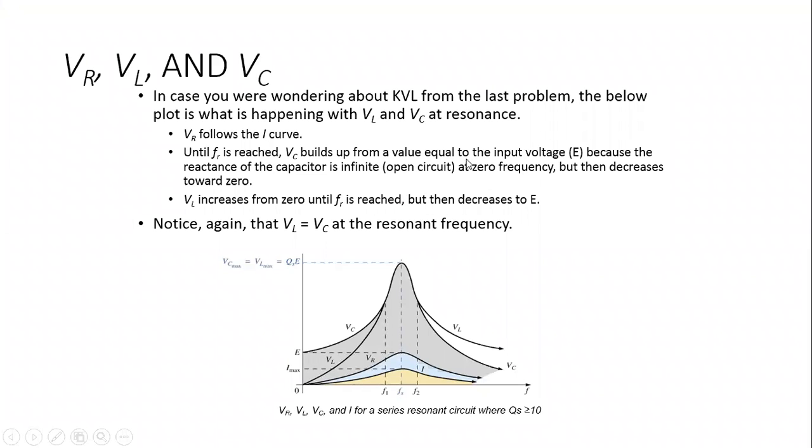So here, by applying KVL to the circuitry, you can plot these things. How can you get the range of the frequency, how can you get the bandwidth, what will be my resonance frequency at a particular point, and the initial and final frequency ranges? We also need to take care whether my voltage is lagging or leading in the capacitor or the inductor. Similarly, I should take care whether I am getting the minimum or the maximum current.